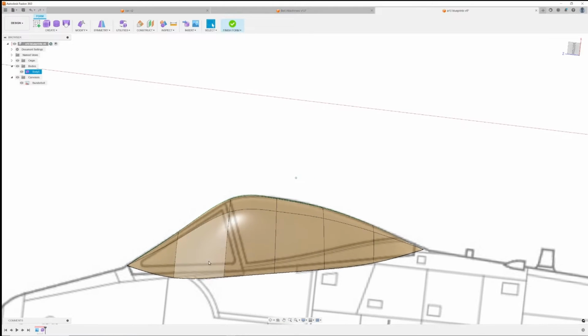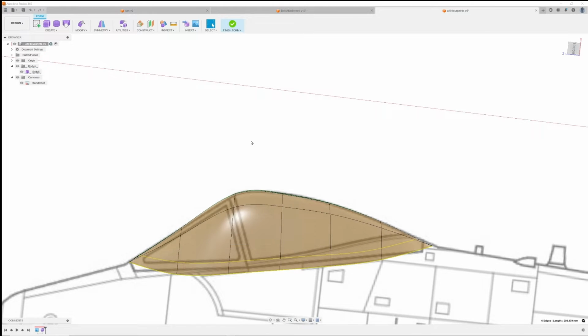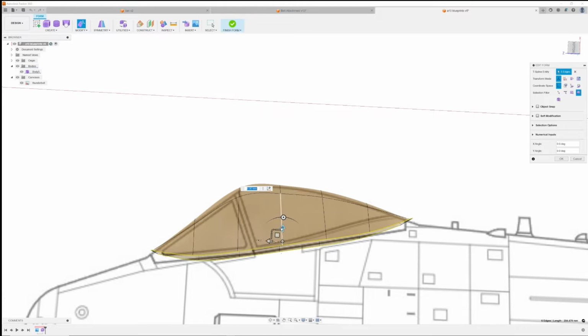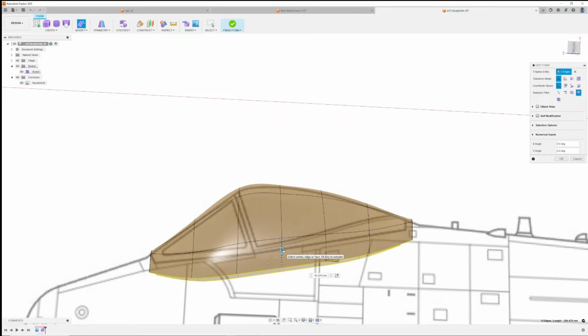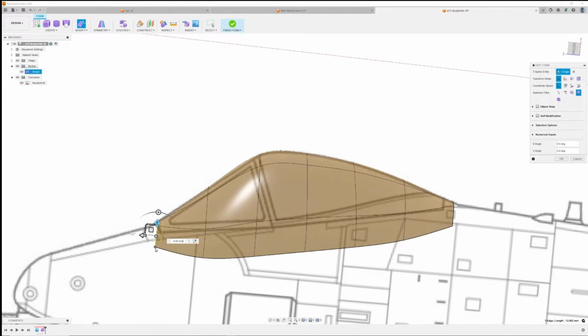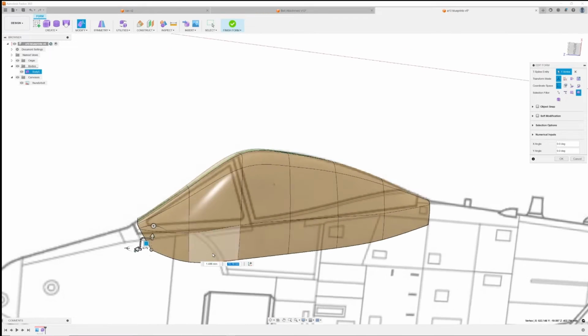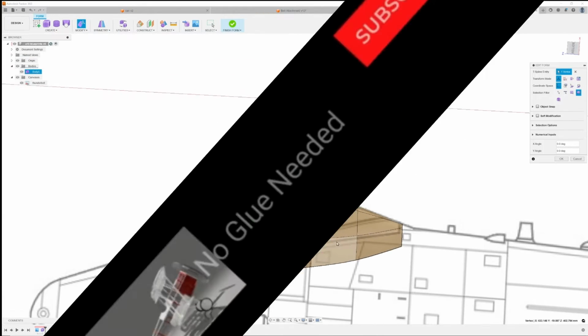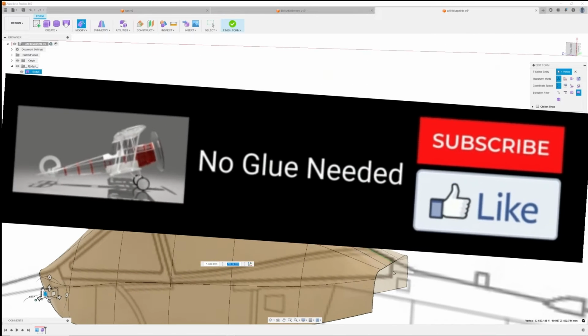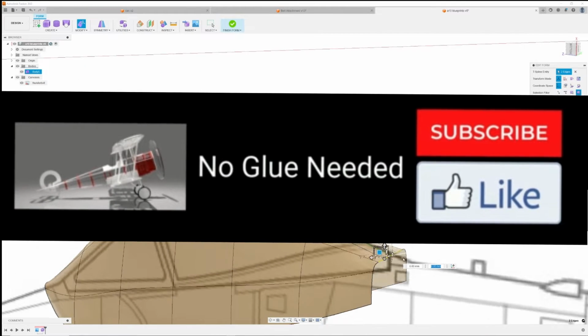I've added another set of faces downward. This extra face will be cut out later in the final design and was added only to ensure coverage. To add the extra set of faces, select the perimeter of the canopy and while the Edit Form command is active, hold down the Alt button and drag the arrow button in the direction you'd like to add the faces.